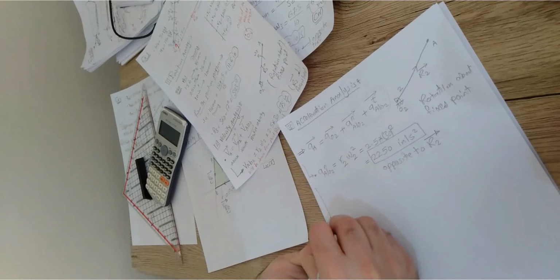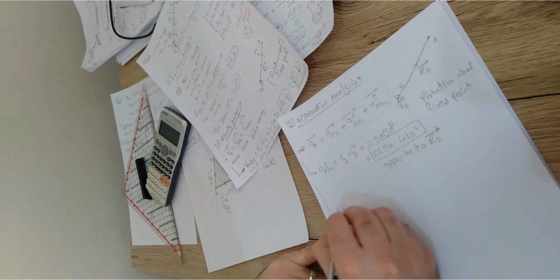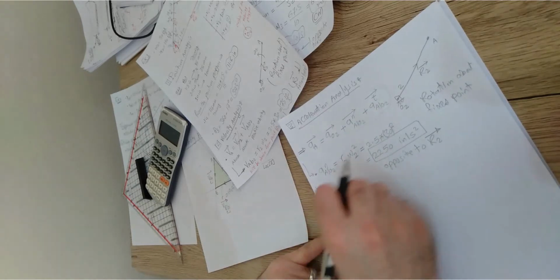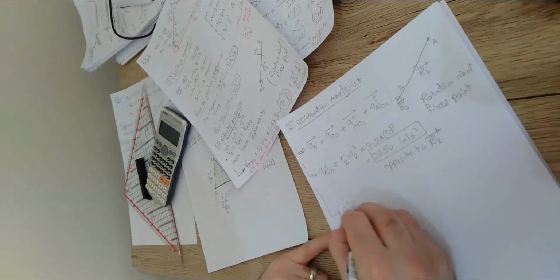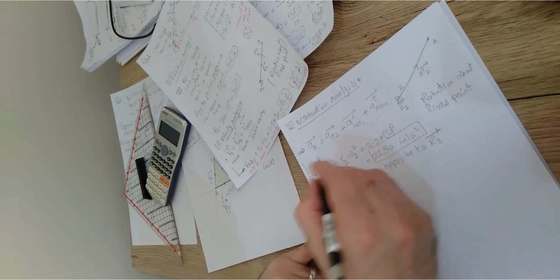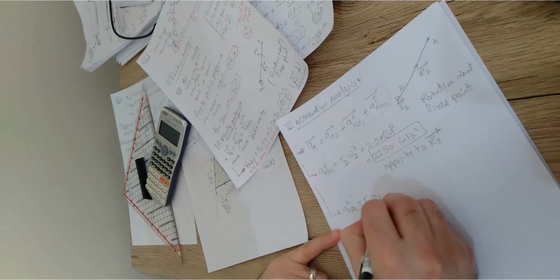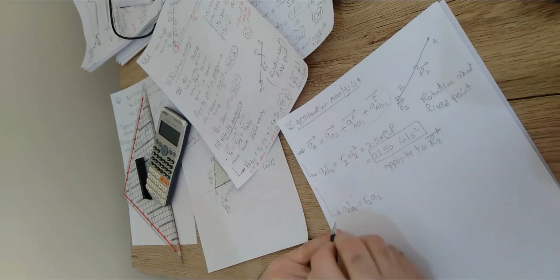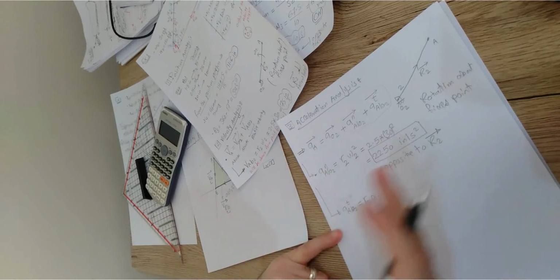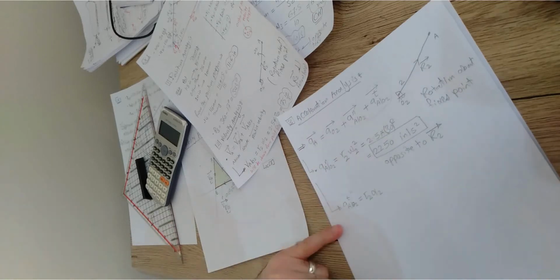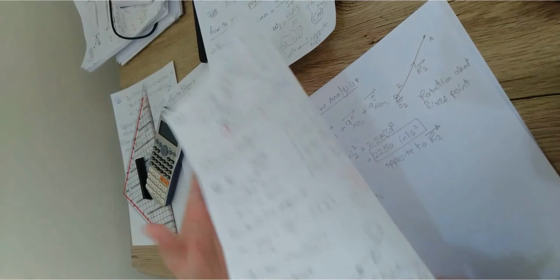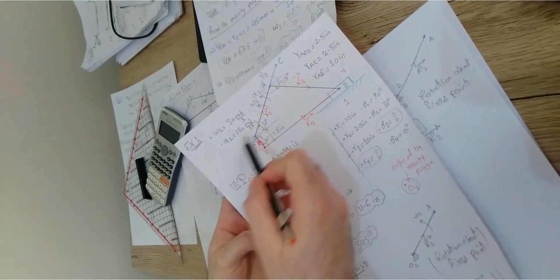And the second component that shall be drawn is the A relative to O2, this relative acceleration tangential component, as a vector. Right? Alright, so here I'm talking about the magnitude. The magnitude should be R2 alpha 2. If you remember from the dynamics class or the complex algebraic method, the tangential component is R times alpha. What is alpha? This is the angular acceleration of length 2. Since I'm talking about length 2, alpha 2 is already given here as 150 radian per second square.